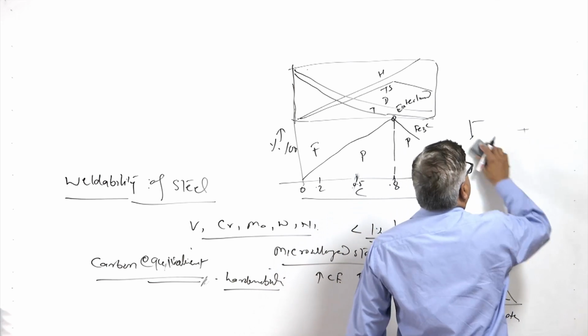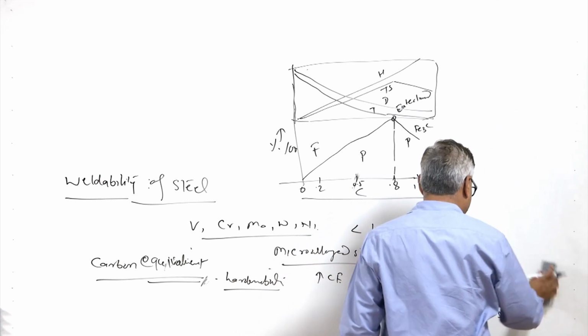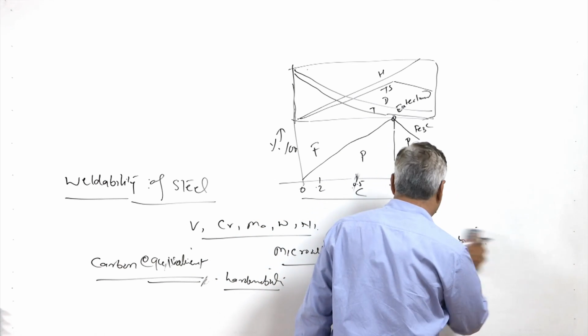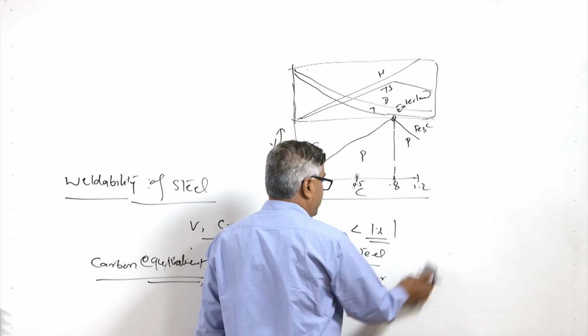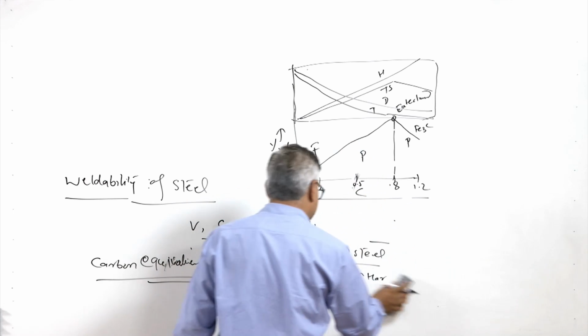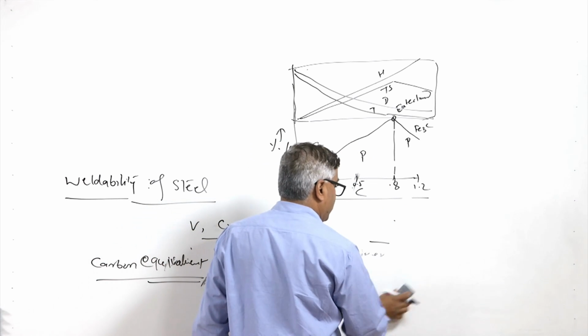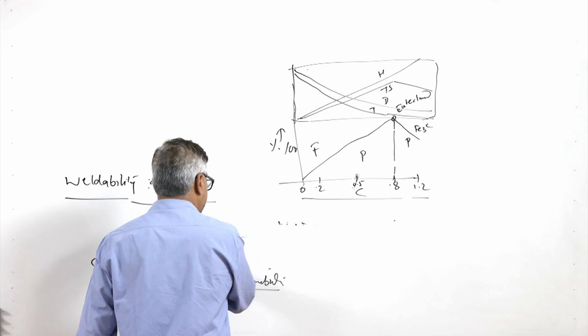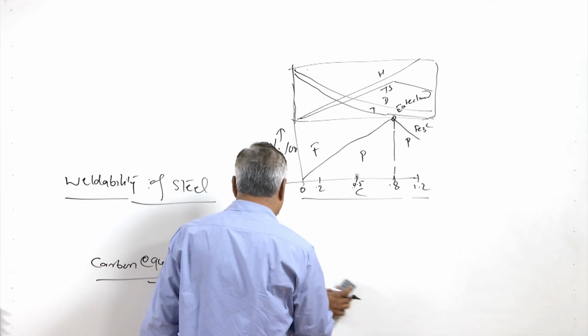This typical test is called the Jominy quench test, and the depth up to which steel is hardened after quenching is used to characterize the hardenability. Greater the hardenability, greater will be the cracking tendency, because of the increased hardness and the residual stresses which are developed during welding.